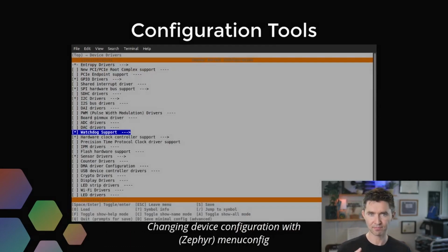In terms of configuration, again, you're going to be trying a lot of different things here, and leaning on configuration tools can really help you to try out a lot of different things. You can, of course, always do this stuff in code, but having some kind of interactive configuration can really help here. I am in Zephyr quite a lot. I'm a big fan of Zephyr, and I really like that they've adopted menuconfig, which is from the Linux world. That allows me to tweak different characteristics within the device, and that's really at the kernel level, but other things like being able to interact with devices over sensor shells, over different shells that are available as well. Interactivity with these things that are out in the world is really, really important, and being able to build that in, leaning on tooling that's already there, can really help you out.